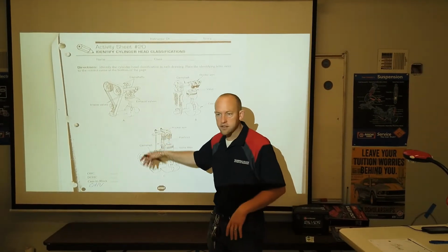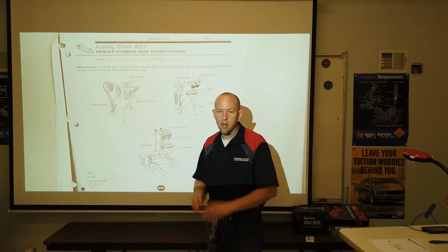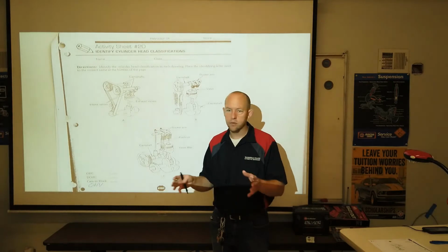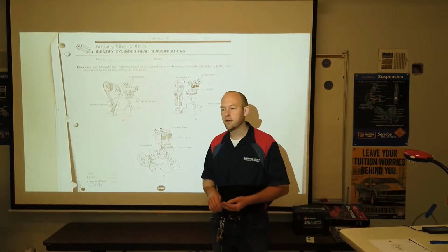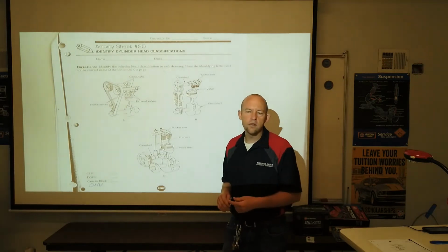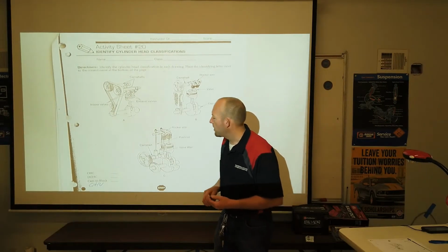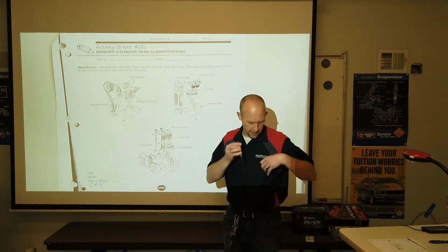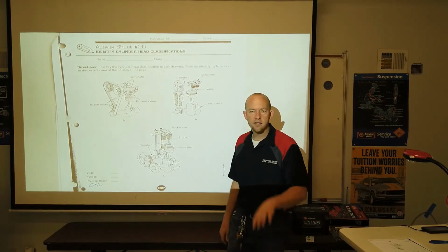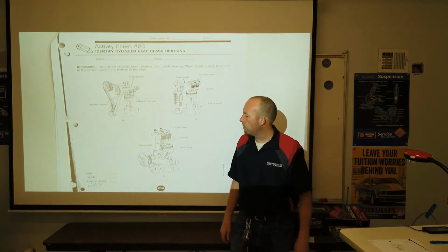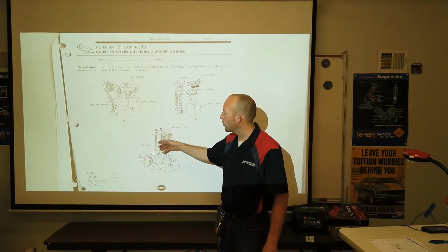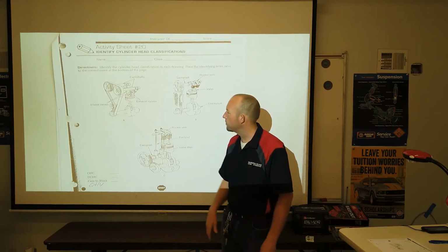Earlier than this, they had the valves in the block, and you would see that with flathead motors. Those are quite old, in the 40s and before that. I don't know if they used them in the 50s or not, but I think they started getting phased out. Maybe there were manufacturers that used them in the 50s. Ask Mr. Posey. But this would be our overhead valve configuration, push rod motor or cam in block, because the cam is in the block.